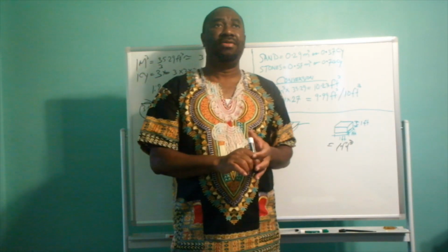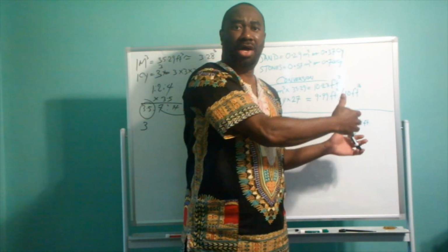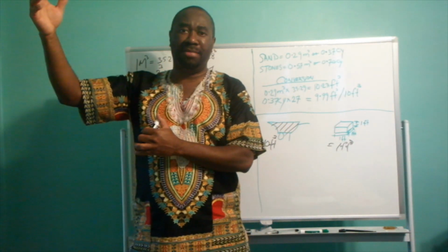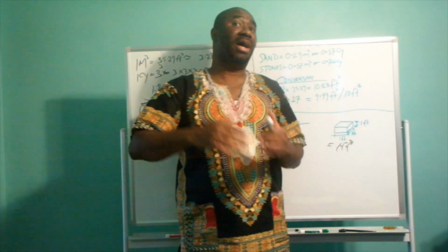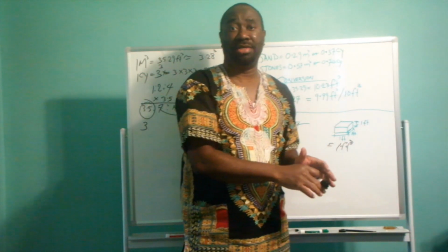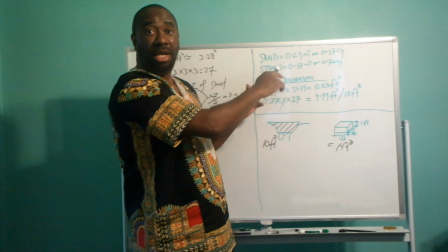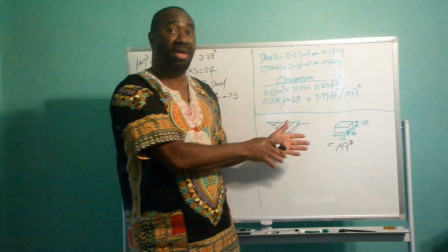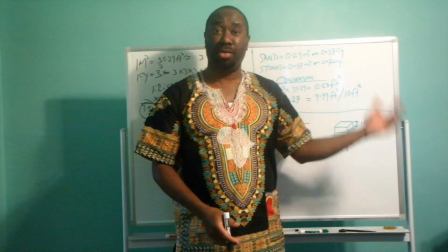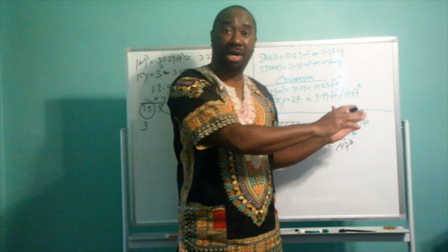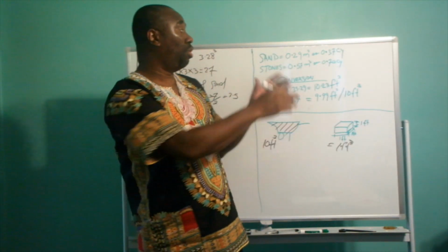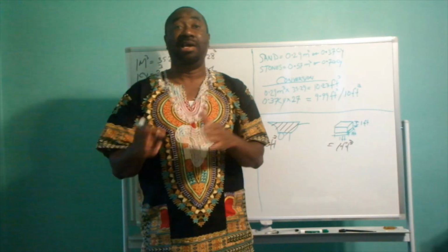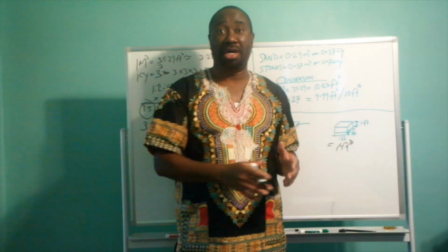So in the event that you're going to the hardware or wherever you buy your material, you do not buy excess of material and you do not buy less. Because if you buy excess, you're going to throw away material that is not going to be used in your concrete, and that's money. And if you get less material to do your concrete mix, you have to make several trips back to the hardware or wherever you buy your aggregate to get the additional amount, and that is going to cost money for transportation. And in another instance, it's going to rob you of productivity on your site.